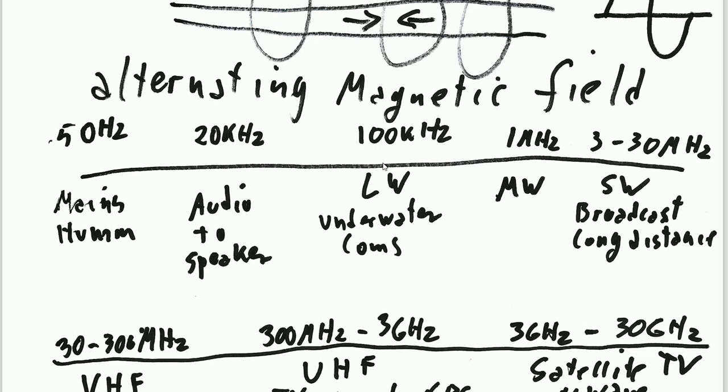and you can hear long wave signals maybe about 1,000 kilometers away without much of a problem. So they follow the curvature of the Earth, and you can transmit beyond the horizon, but the band available is very, very little. As you go further down, you go to 30, 40, 50, 60 kilohertz. In between those two allocations, the waves can even penetrate water.